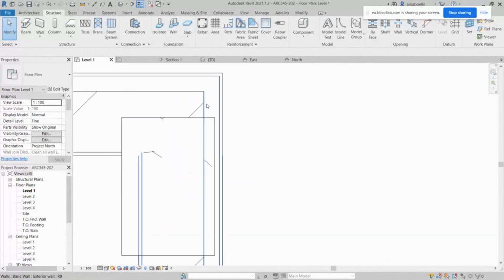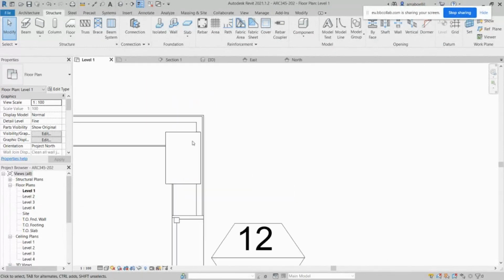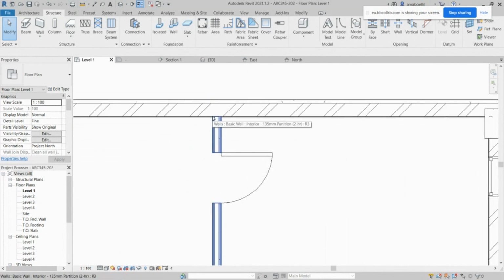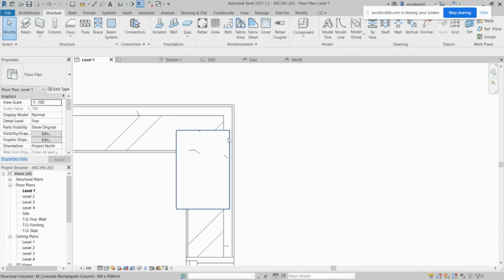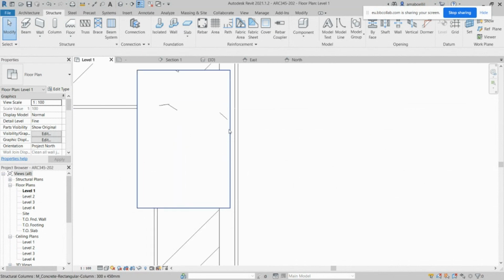The other problem comes when you have a thickness or a layer that you cannot adjust for less than this, similar to the problem of the door. You remember that I said it's better to have one brick complete before placing the door in order for the construction or the mason to do it well. Here also the same thing. Suppose you have a layer here that you cannot divide into half. When you place this column at the edge here or at the surface of the wall, when it meets the column, you will run into a problem. You don't know what to do.